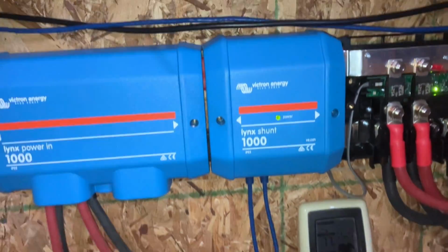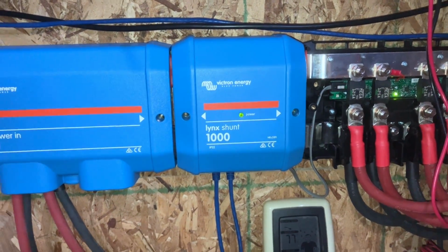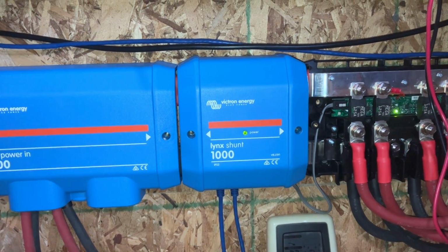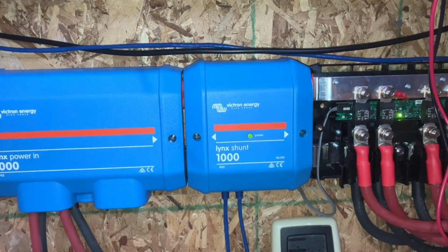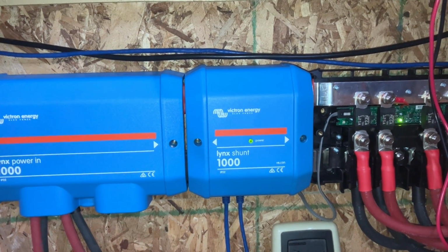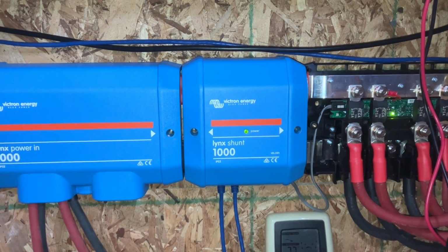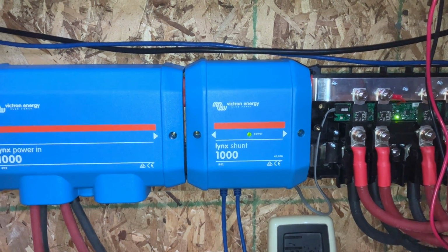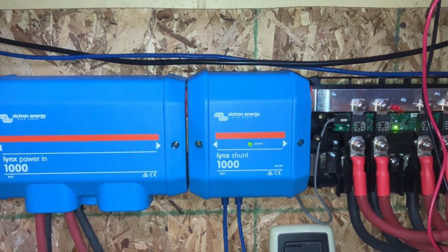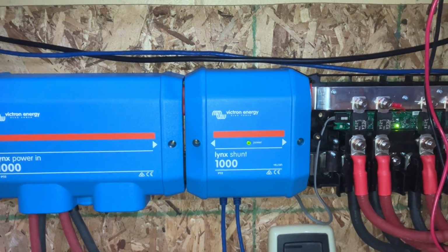And that really ends up helping, because we looked at it before, the voltage value on the link shunt is like 150 to 250 millivolts different from what I read off of the bus bars. So all the different devices are reading different voltages, but if I share the voltage from the shunt, then all the inverters and the charge controllers see that same voltage based on the shunt voltage.